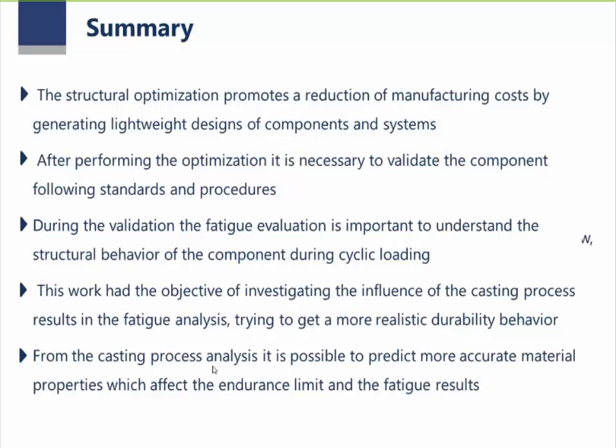From the casting process, you can take some properties, for example, the tensile strength of the material, which will vary from part to part of the component, and this also affects the fatigue results, because the endurance limit of the material is related to this variation of the tensile strength.